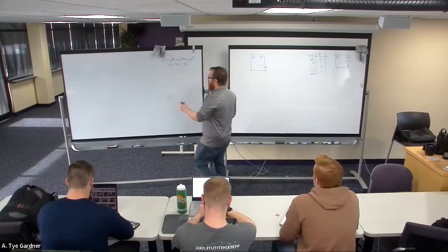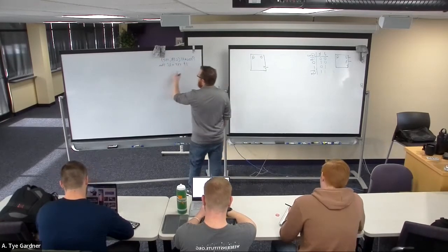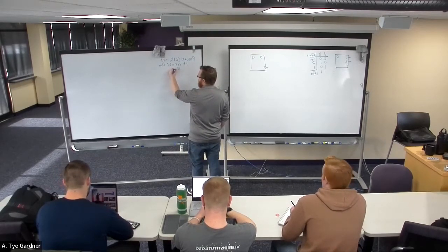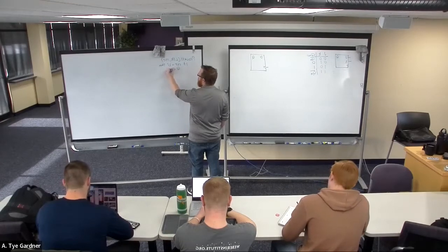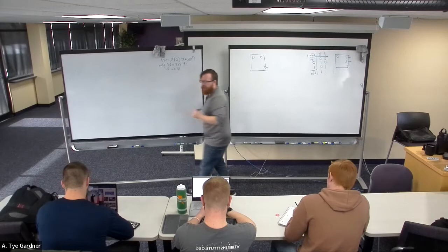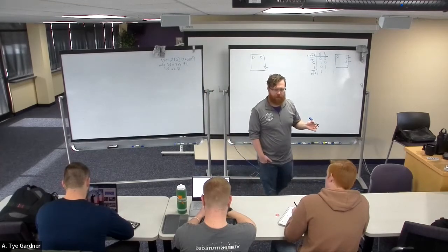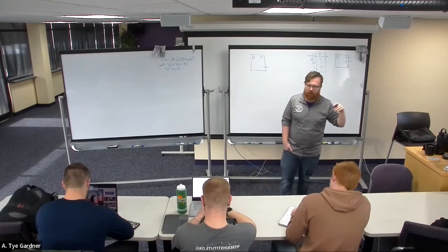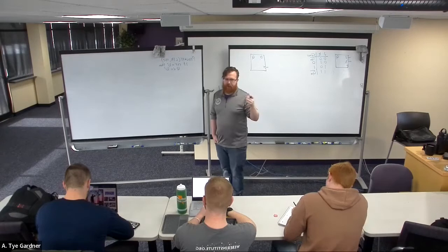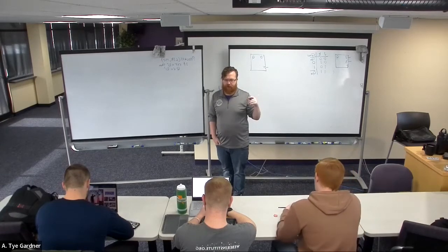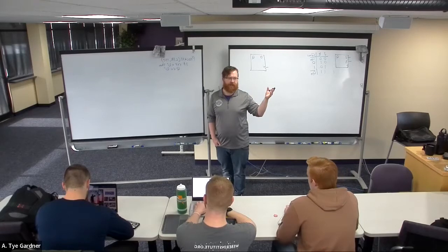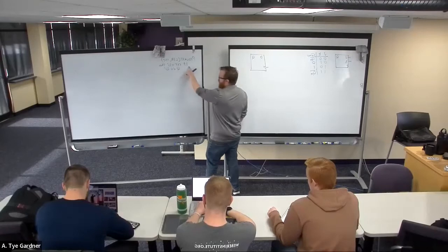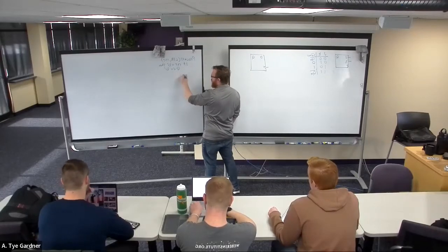And what does reset mean? It means that I want my output Q, and let's just call it Q, and we'll address that issue later. Q gets assigned to 0. There are apostrophes because it's a bit, or quotes for when it's a standard logic vector. Many of you, when you define vectors, are still making the mistake of not defining the size when you declare the signal. Don't forget, you always have to tell the standard logic vectors how big they are. But here, if we're resetting, let's go to 0.